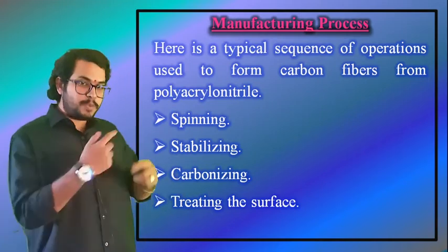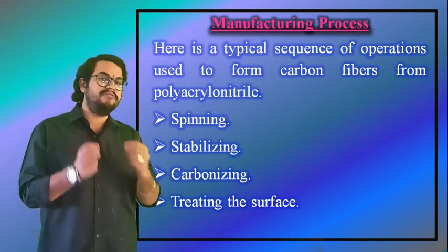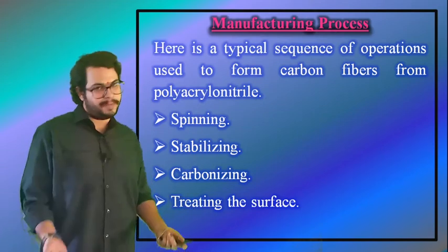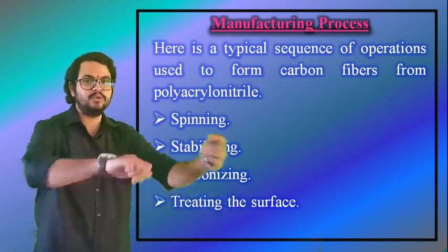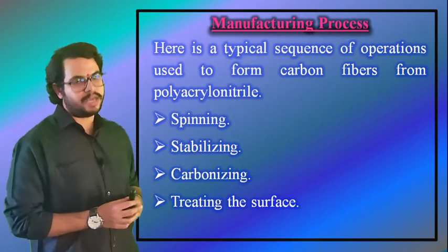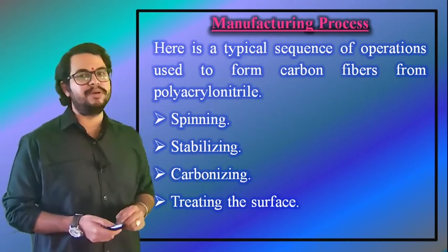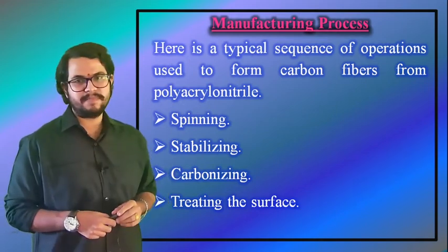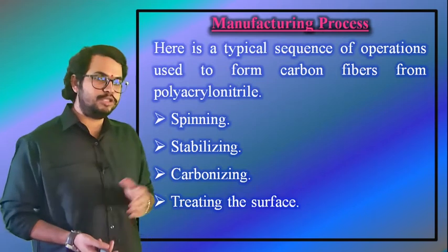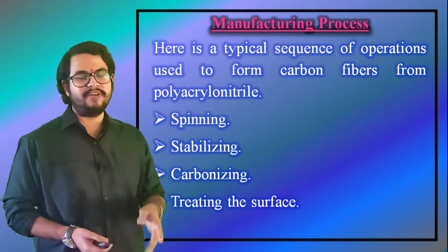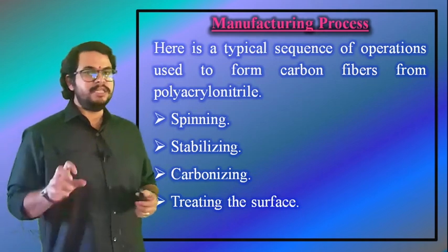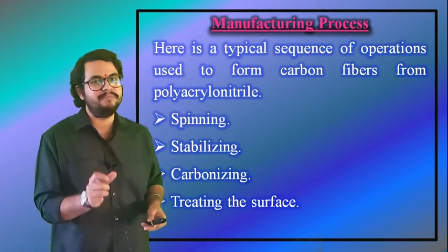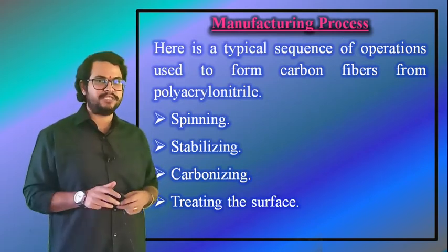The plastic is then spun into the fibers using one of several different methods. In some methods, the plastic is mixed with certain chemicals and pumped through tiny jets into a chemical bath or quench chamber where the plastic coagulates and solidifies into fibers. This is similar to the process used to form polyacrylic textile fibers. In other methods, the plastic mixture is heated and pumped through tiny jets into a chamber where the solvents evaporate,